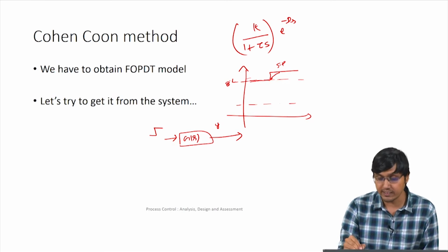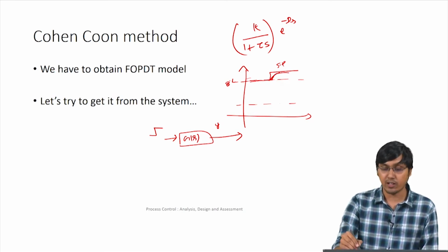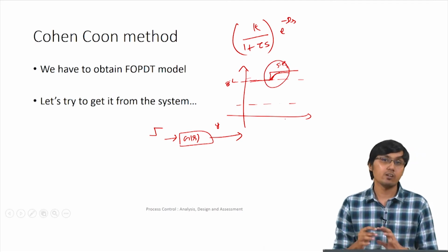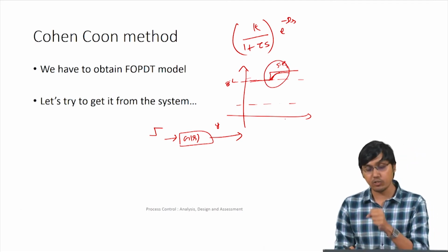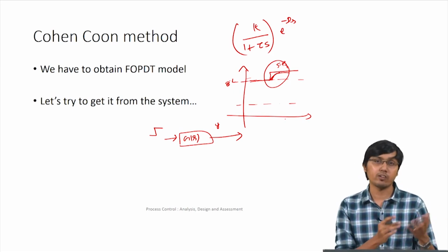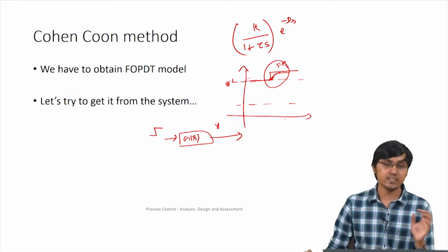So this is going to vary something like this. Now with this, can I get a model? My objective is to do this experiment to get a model, basically to get some coefficients, and then use these coefficients or the model to get some PID values, so some Kp, Ki, Kd values. That's what is happening here. So this is the Cohen method.